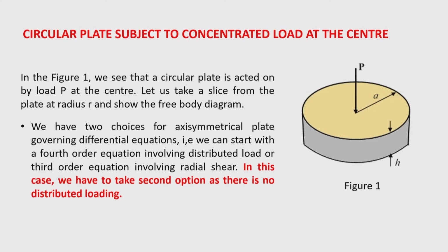In fact, there is no load which is truly concentrated; any load has some distributed area. So, practically if such a load occurs in the plate, especially a concentrated load at the center, then we can find the bending moment in the vicinity of the load, take it to the right and left of the load, and take the average of these two quantities to find the bending moment at the center. Okay. So, let us go to the topic.